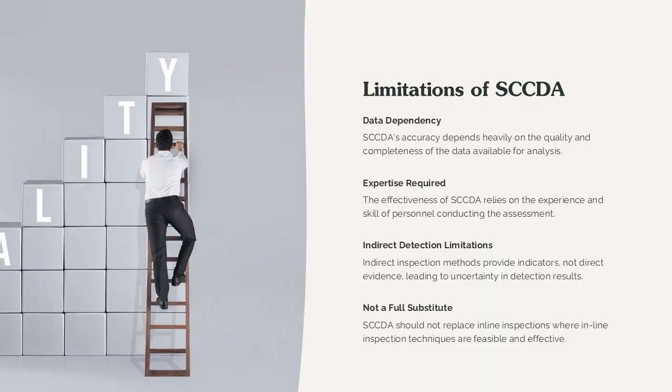Despite its benefits, SCCDA has inherent limitations that must be recognized. The methodology is highly dependent on the quality and completeness of available data, as well as the expertise of the personnel performing the assessment. SCCDA does not guarantee detection of all SCC and should not be viewed as a full substitute for inline inspection where ILI is feasible and effective.